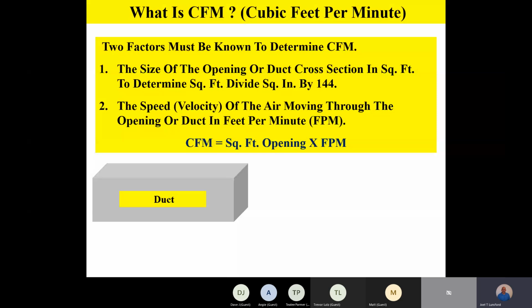And then if we look at the very top of the duct calculator, the friction loss, we find that at 500 CFM, with that size duct, it looks like we're going to have a friction loss of about 0.03, about a 0.04 inches of water column. This is all in inches of water column, the friction loss per 100 feet of duct.